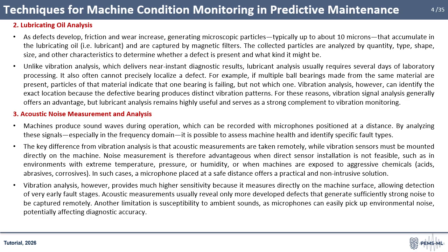or aggressive chemicals. However, vibration analysis is more sensitive, as it measures directly on the machine's surface and can detect very early-stage faults. Acoustic analysis can identify more advanced defects that generate strong noise. Also, acoustic analysis is susceptible to ambient environmental sounds, which can reduce diagnostic accuracy.